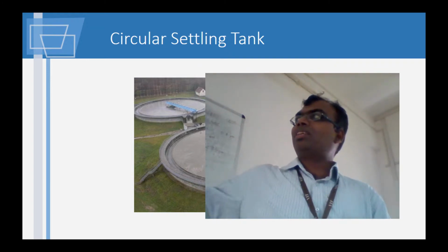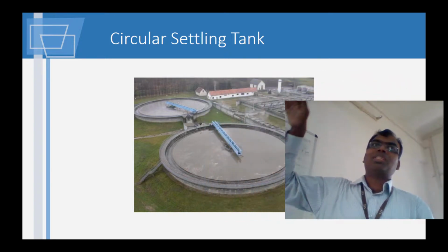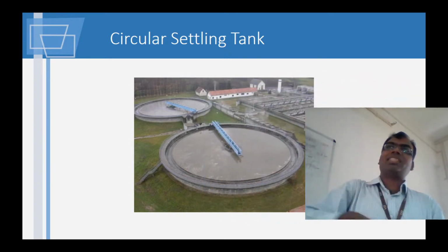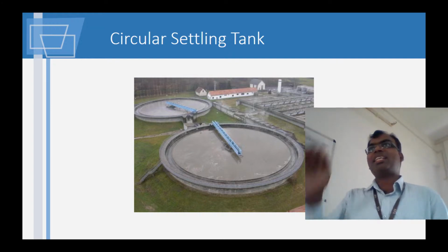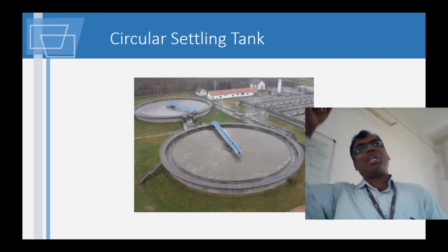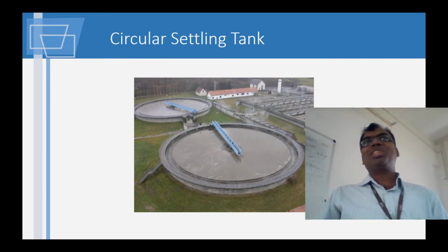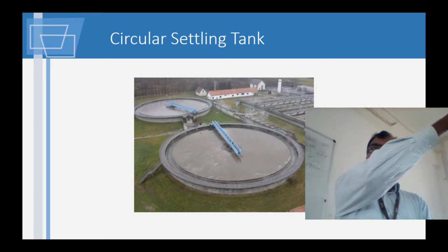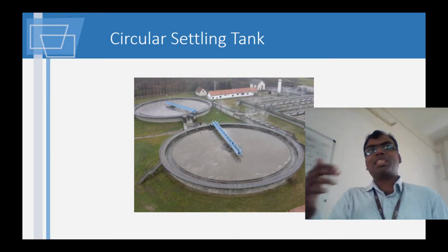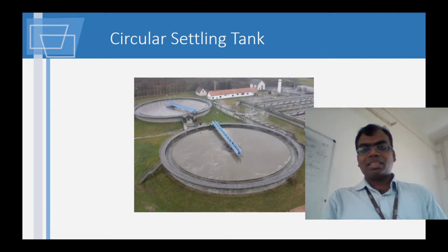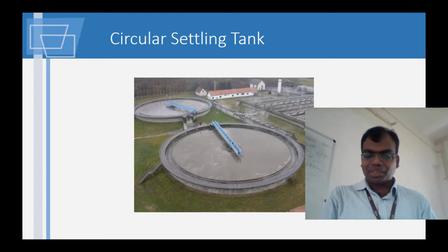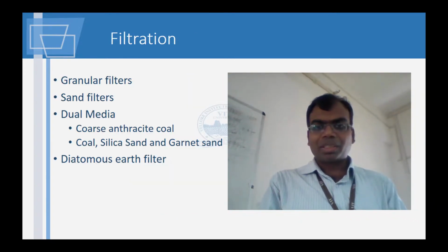But basically, the water as it flows will have the solids settle. So you have a higher depth at the middle, so large particles can immediately settle. Smaller particles might go to the side, but again you have slope so that all the particles can be brought back to the center. Okay. So I just wanted to revisit this slide in particular.